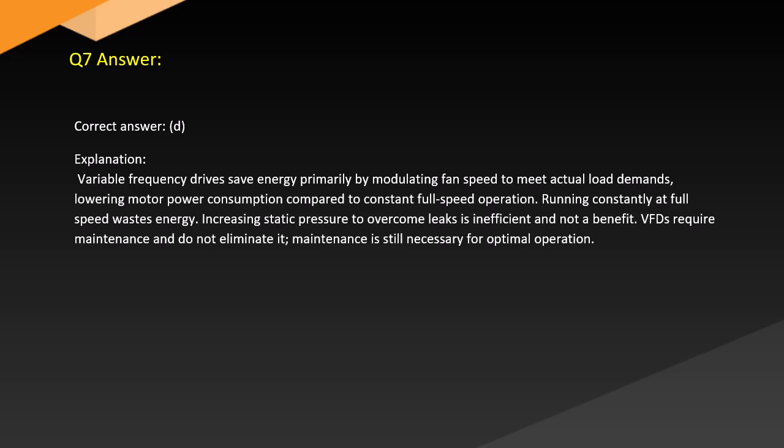Increasing static pressure to overcome leaks is inefficient and not a benefit. VFDs require maintenance and do not eliminate it. Maintenance is still necessary for operation.